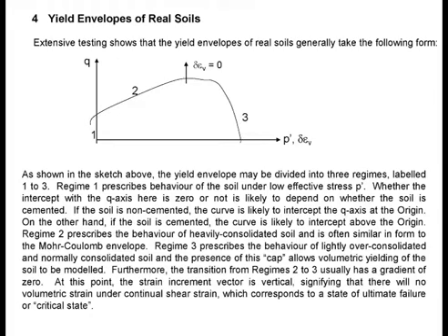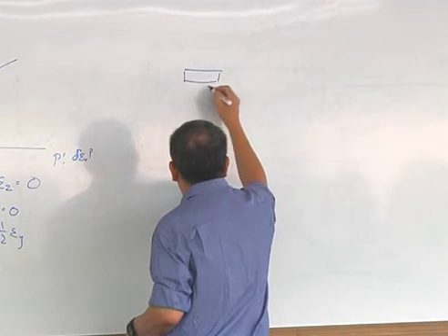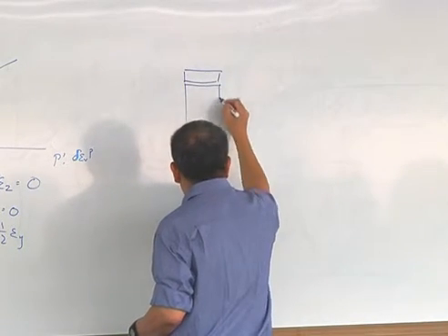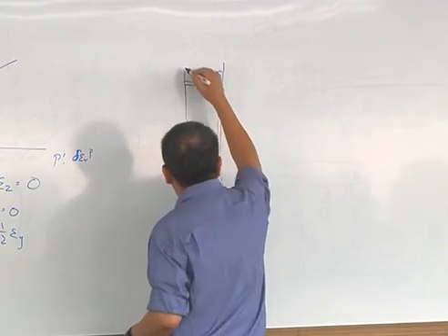If you have a triaxial test specimen, how many of you are doing triaxial tests or have done triaxial tests? Okay. Now, if you do very, very low effective stress, what happens is this. If you look at your triaxial test specimen, this is the end cap, this is the specimen, that is the bottom platen, and then you have a rubber membrane that comes down like that.